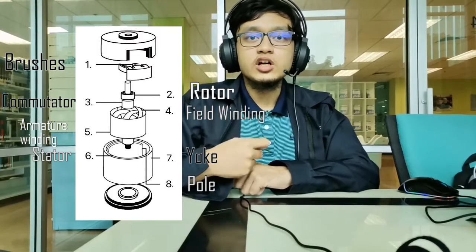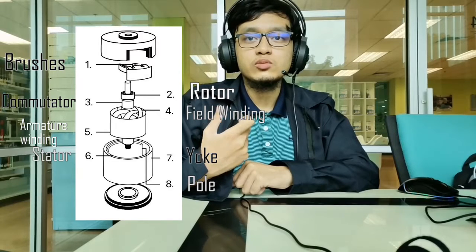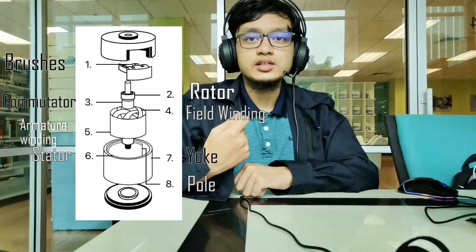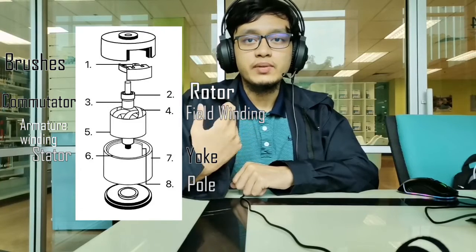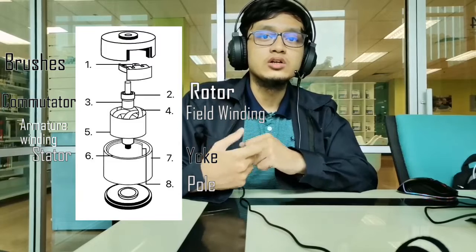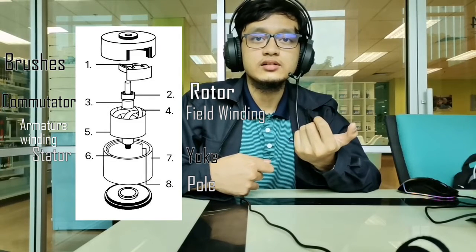A commutator assures that the current from the generator always flows in one direction only. The commutator picks up the current generated in the winding, reversing the direction of the current with each half turn, serving as a mechanical rectifier to convert the alternating current from the winding to unidirectional direct current in the external load circuit.